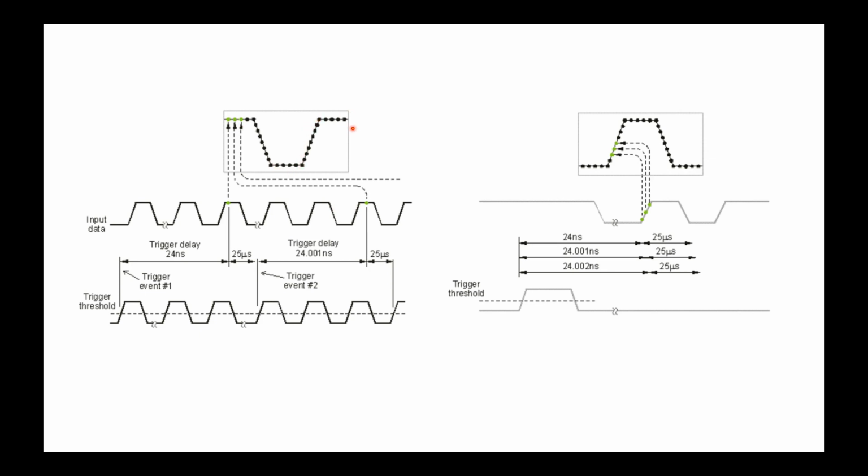Now, there's also another trick here. You have to make sure that the clock for the trigger circuitry is synchronous and coherent and locked to the input signal frequency. Otherwise, you also cannot do this. So this makes the setup quite a bit more complicated, because now not only do you have to have a synchronous clock available, you also have to have your input signal be periodic. But the trick is that the instrument ensures that this step in time is extremely precise.